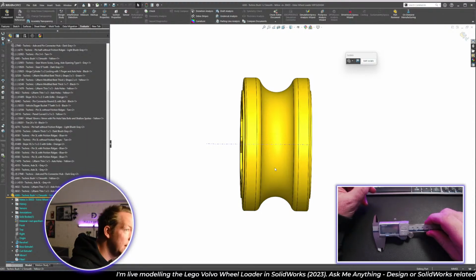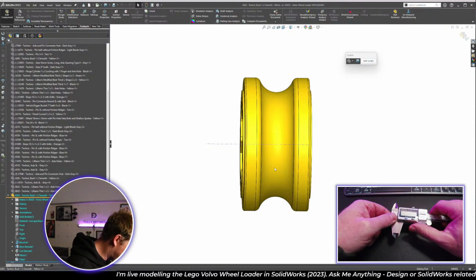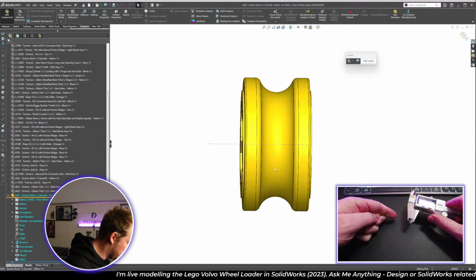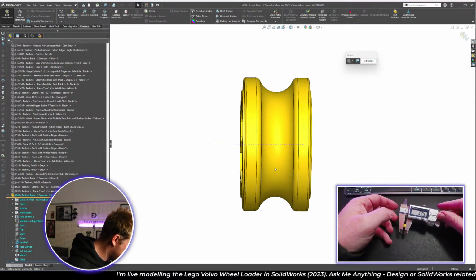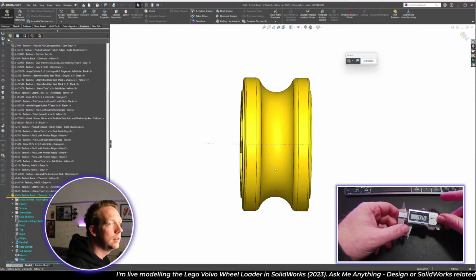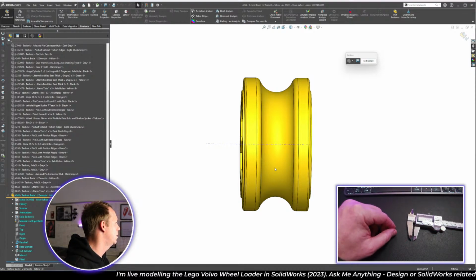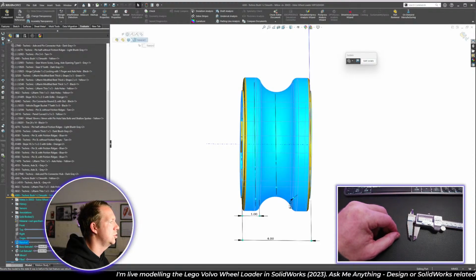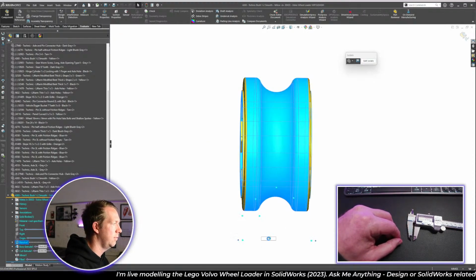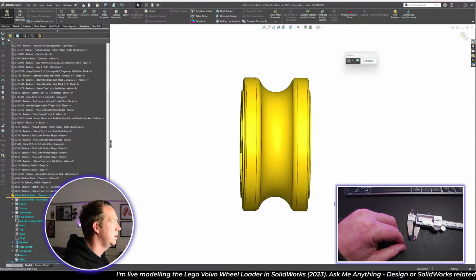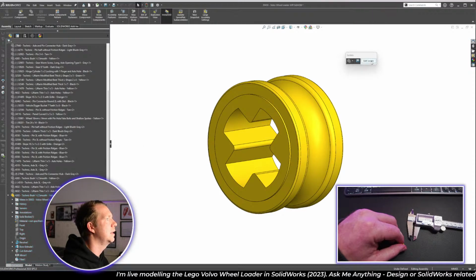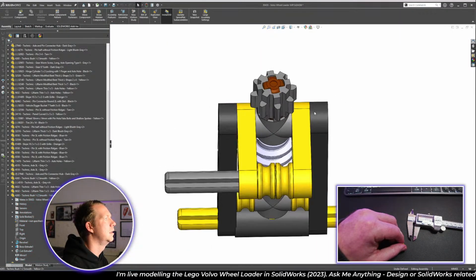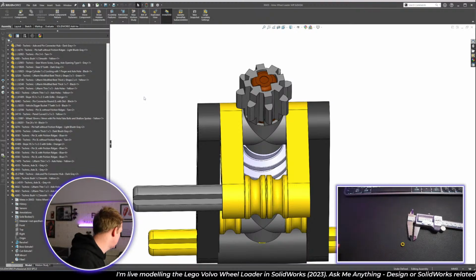What is it actually? So these calipers are much more accurate than what we'd used previously. Its actual width is 3.95. Not bad. Okay, so I'm going to change this to 3.95. Tiny bit smaller, everything else can stay the same. Exit isolate. And save.